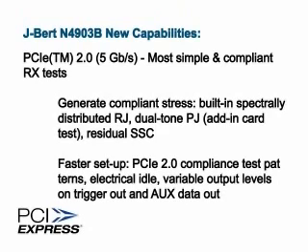For PCI Express Generation 2, it's the most integrated and simple measurement setup for compliance testing of receivers. You can generate all the compliance stress conditions with the J-BERT, and due to its built-in compliance patterns, electrical idle state, and variable output levels on all supplementary outputs, also the setup time for the compliance test is reduced significantly.